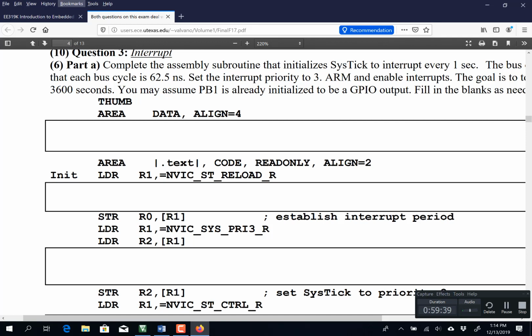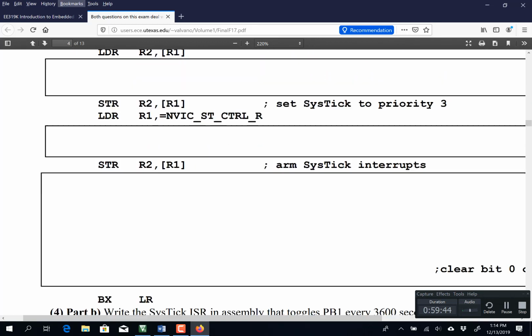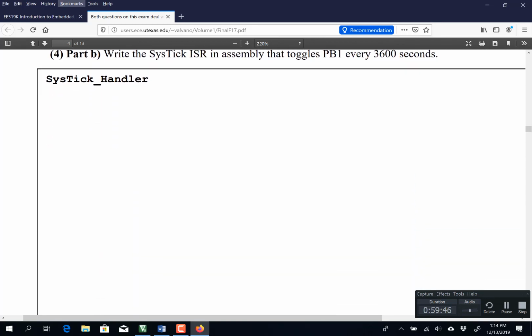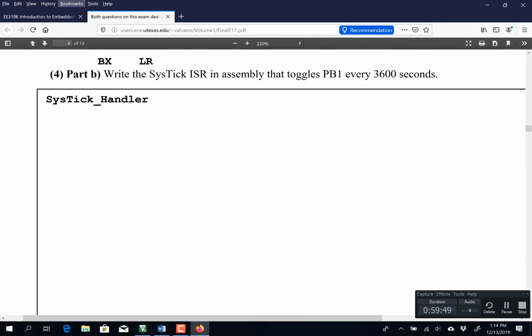Yeah, but in the last one, the SysTick number... What we normally do is we check the 16th bit of the current. No, you don't. You don't check anything. The 16th bit of current causes the interrupt. That's the flag. Yeah, but that's with interrupts, you don't check the 16th bit. The 16th bit, the count bit, caused the interrupt. Yeah, when you see here, no backward jumps.